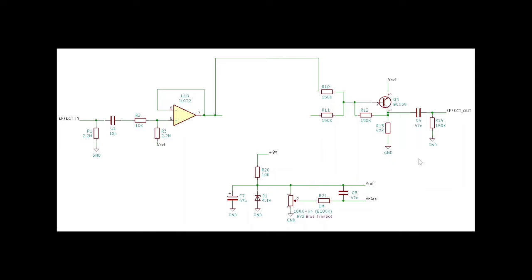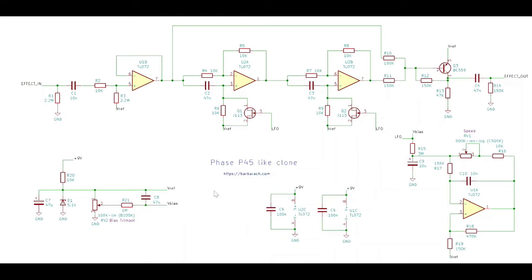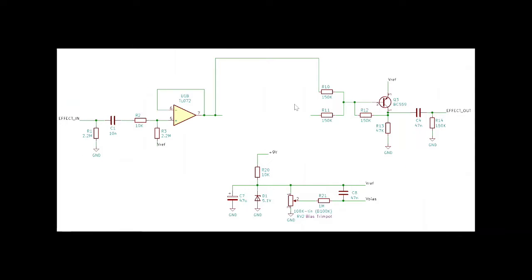The power supply is slightly different. So here we have this power supply section. If you think about it, we will use JFETs at some stage if you look at here. So they need to be biased as well, and we need reference values for our op amps. So that gives us two sort of reference slash bias voltages, where normally we had only one for op amps so far.